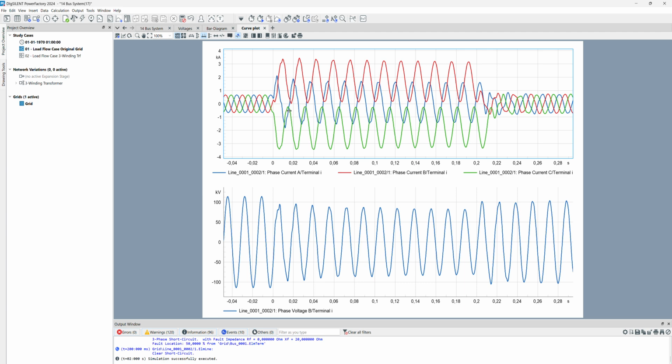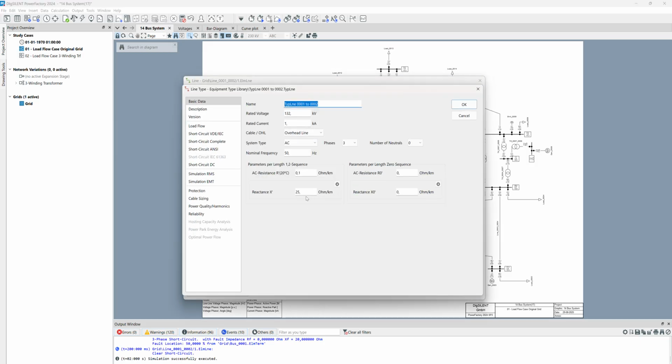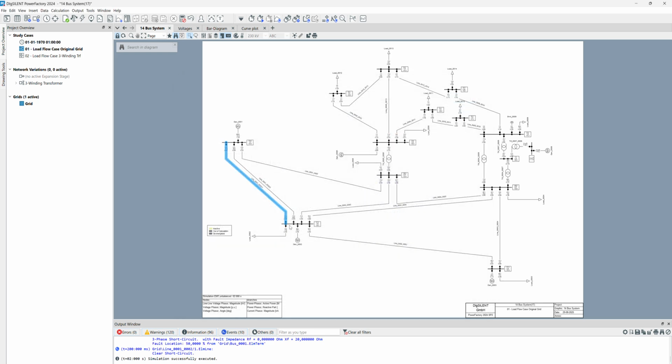So in this situation, we can have opening of the circuit breakers, but if for other phases also we don't have any zero crossing point, then the circuit breaker cannot open the line. So in these situations, normally if we have the phenomenon that all three phases don't have any zero crossing point, normally the reason is the wrong ratio, the very high ratio of X to R. Normally we should insert a resistance with the circuit breaker into the line.